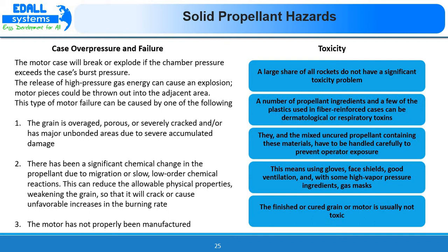They and the mixed uncured propellant containing these materials have to be handled carefully to prevent operator exposure. Also, this is toxic, so the personnel who are handling the propellant should be given proper treatment and regular tests have to be carried out. This means using gloves, face shields, good ventilation, and with some high vapor pressure ingredients, gas masks.